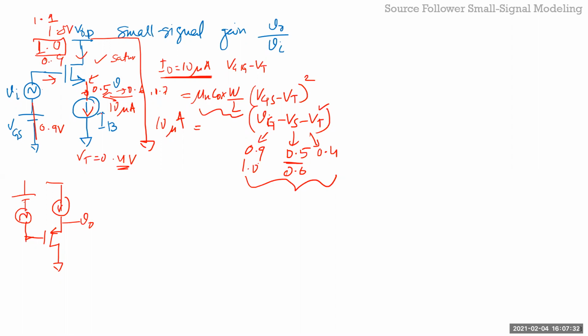So for example, you want to drive an 8 ohm speaker from your cell phone. Have you ever tried that? Well, you'll get nothing. It'll be just like a headphone. So you can take that 8 ohm speaker and put it by your ear, because that's the power it can deliver, right? Your headphone usually requires about 200 milliwatts of power and just 32 ohms. So it just delivers 32 milliwatts of power because it just has that much current juice in it to deliver. You want to put an 8 ohms, you have the voltage, but don't have current to supply.